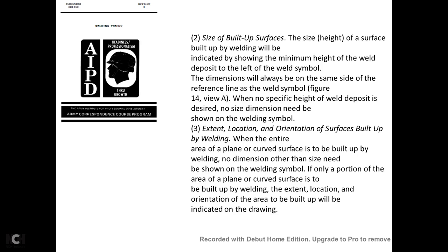They have no specific height of the welding deposit desired. No size dimension needs to be shown on the welding symbol. 3. The extent, location, and orientation of the surface built up by the welding.